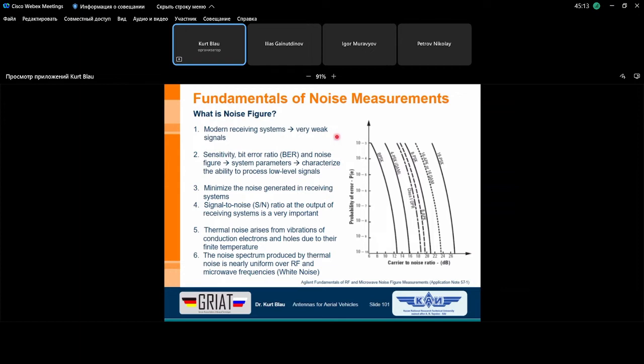And I showed you some examples regarding the so-called carrier to noise ratio. It means the carrier is a sinusoidal signal which is modulated with the wished information. And here several different modulation schemes were shown. For instance, a very simple one was BPSK, which is only a phase switch between plus and minus 90 degree, exactly opposite phase.